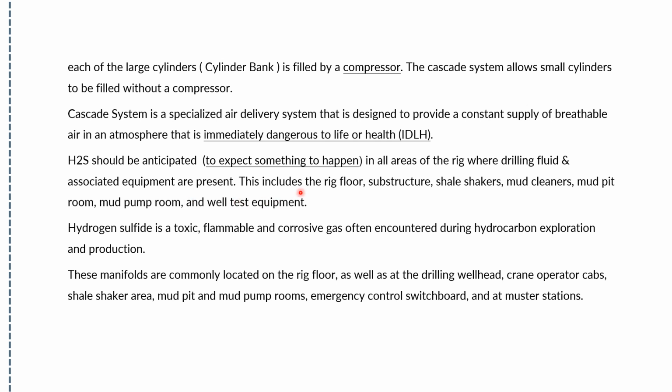Why? Because the drilling fluid is coming back from the bottom of the downhole, so hydrocarbon gas and H2S might be coming with the returning mud as it goes through the mud treating equipment. These are the locations where there is a chance of a leak of H2S gas.